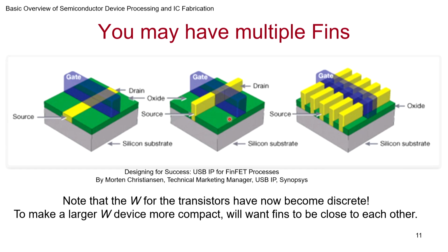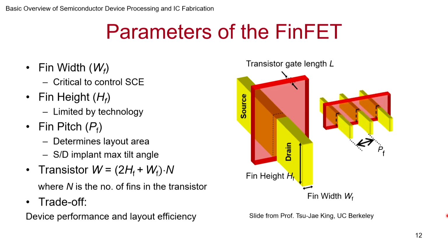So this FinFET or three-sided gate around 22 nanometers or so, Intel started implementing it in 2011, and later when they went forward, many times the next generation, all that it did was it brought these fins closer to each other. So for example, if I'm not wrong, in 14 nanometers and 11 nanometers, one of the main differences is that the fins came closer to each other. You are able to implement it very reliably next to each other. So that's one of the key aspects of this. So I hope now you have a feel for what FinFET is.